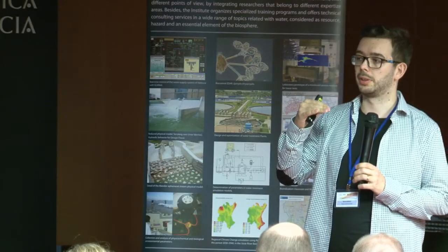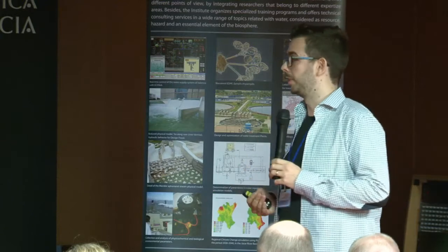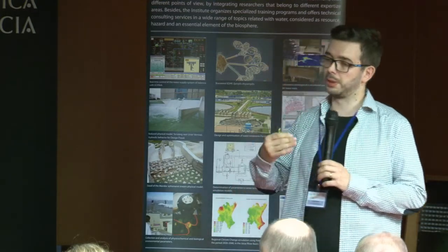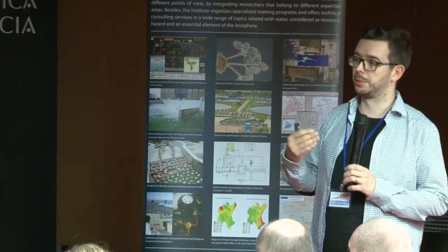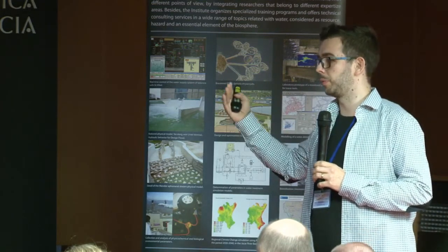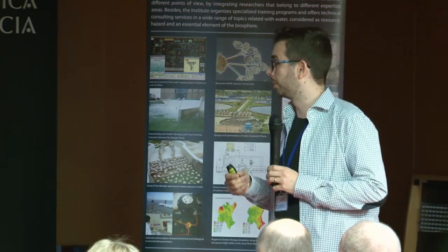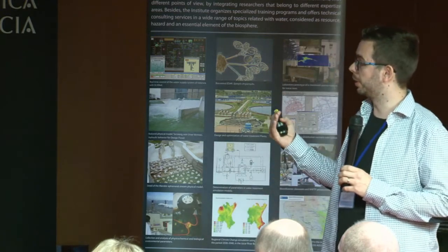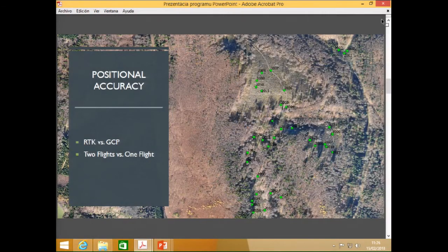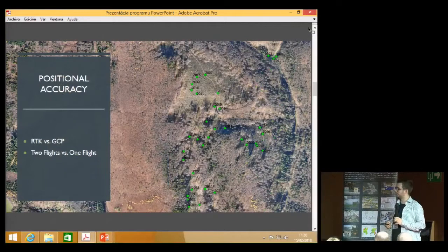the digital terrain model, because as we know, it is very difficult to obtain a digital terrain model from photogrammetry in forested areas, of course. And also we have this flight during the leaf-off season. So we are hoping that the digital terrain model is going to somehow appear, but the preliminary results are showing that it's not the case, even for the two flights.